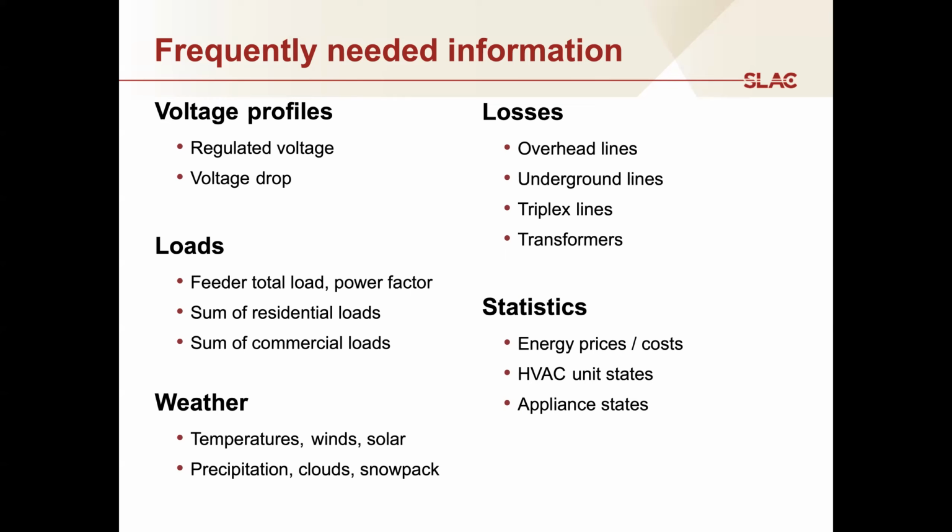So if you're running a simulation where you want to provide the loads on the individual buildings, that is something that you can do from AMI data. You can generate load models from that data. You could generate loads from a physical model that is not reliant on data, but instead reliant on the building's design, right? What is its size? What kind of system does it have? How is it occupied? And all of that can give rise to feeder loads and power factor information that is useful in studying how, for example, voltage controls might be implemented more efficiently.